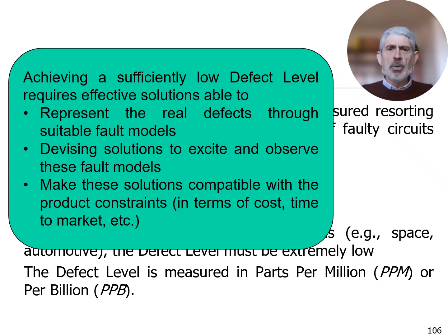Clearly, if I want to achieve a sufficiently low defect level, it will be a long path. It requires using suitable fault models, really able to represent the real defects. It means using solutions to observe these fault models very well, generating test vectors, and applying these test vectors.